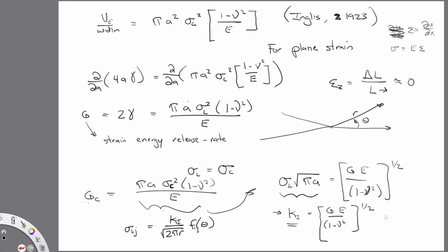And so what the model predicts, you can see just from this, is stress as a function of the square root of r, right? So as r moves away from the crack tip, since it's the square root, you're going to have this decay behavior. But at the crack tip itself, it's undefined. So the crack tip would be at r equals 0.